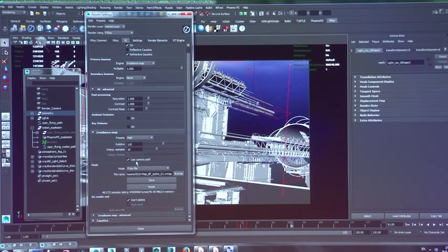Then save this GI, and I will safely have all the static geometry baked into one map. And I rendered this only once, but I have 120 frames of animation, so I saved 120 times rendering the GI. Also, for the rest of the part which was not animated, there is a way in V-Ray to pre-calculate the GI only for these moving parts, so that you have a proper GI solution.